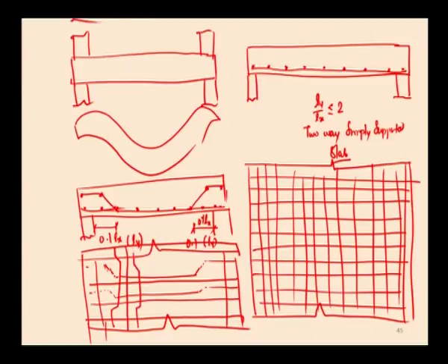Here also the main reinforcement has to be cranked over the support at 0.1 L from the face of the support. So, alternate bars have to be cranked over the support along both the directions and brought to the top to resist the tension over the support along both the directions. This is in the case of two-way slabs.